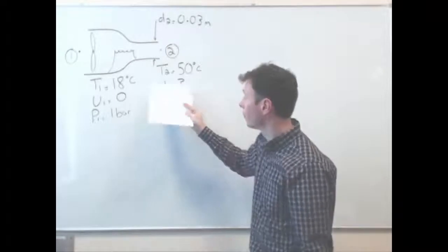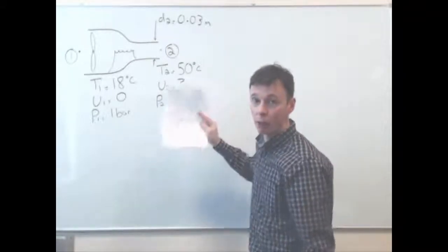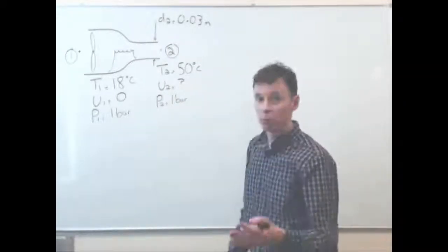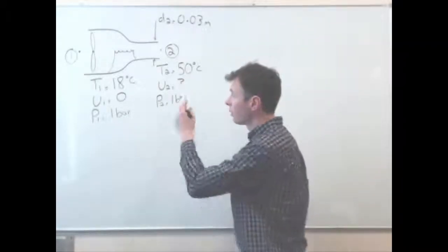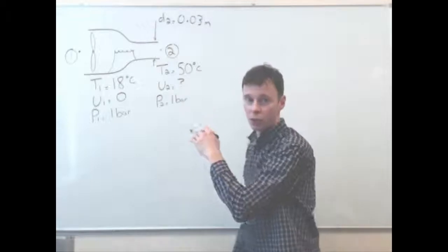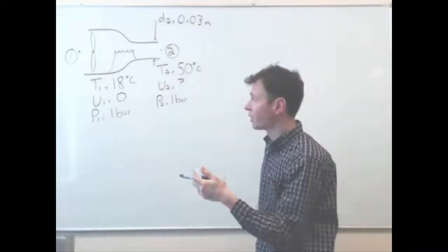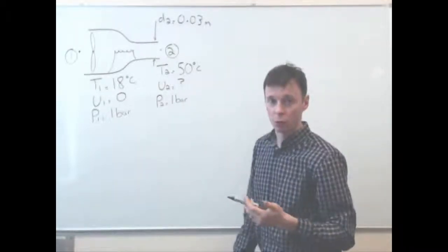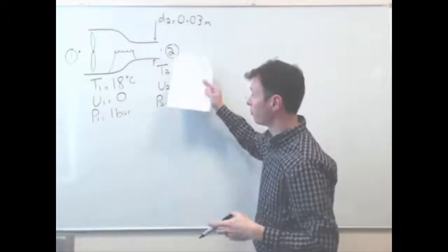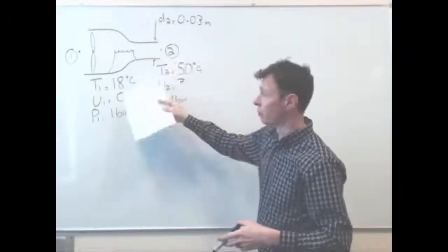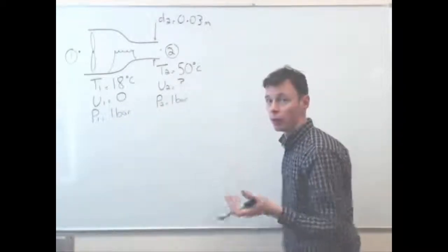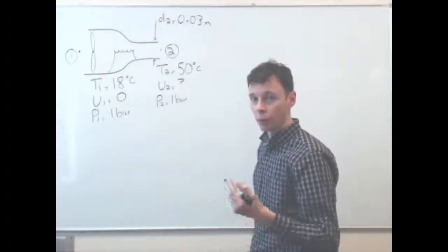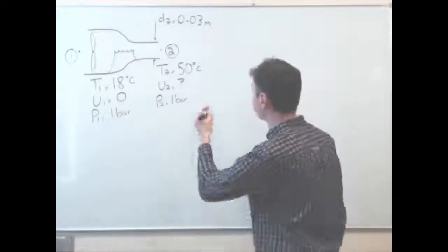The temperature is not enormously high, so around 1.1 roughly. You can use the numbers and your general knowledge as an engineer to guesstimate what the answer should be. If we get a value of more than the inlet density, we know we've gone wrong. So we can use the property of state equation for an ideal gas.